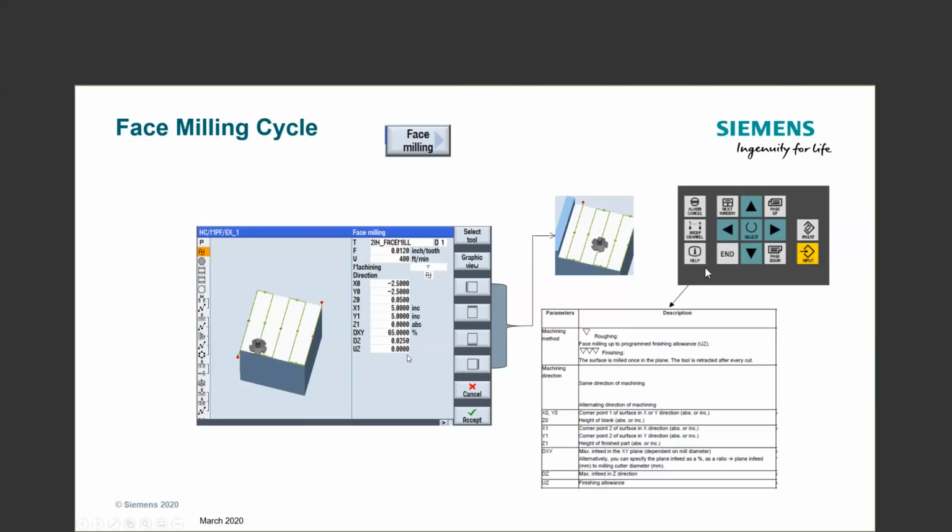In addition, in the face milling cycle, you also have these modifiers on the right-hand side. So this gives us some extra flexibility as far as protecting edges, whether you wanted to maintain a wall, or maybe you have some clamping on 1 or 2 sides, or wherever.